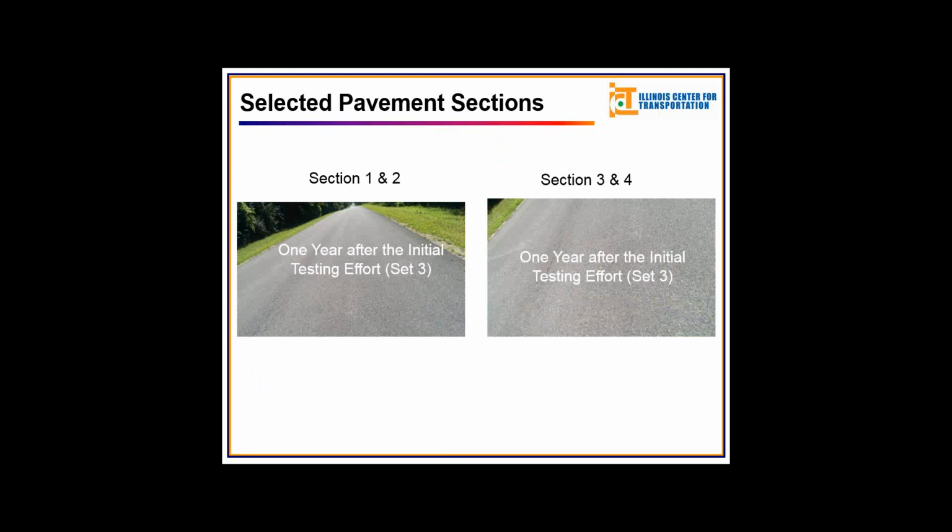Well, we normalize deflections to 68 degrees Fahrenheit, for the AASHTO, yes. How do you normalize the temperature? For the AASHTO one, I use their chart. They have this chart based on the center deflection.